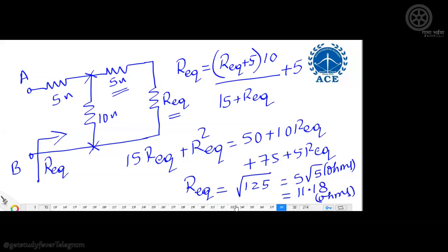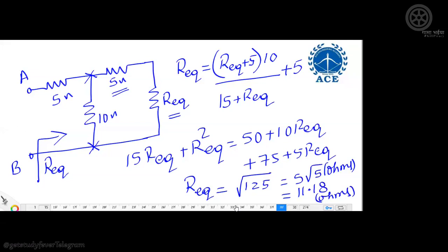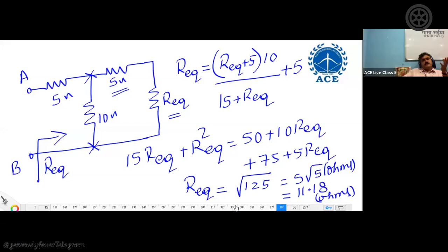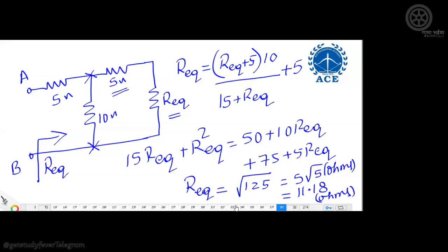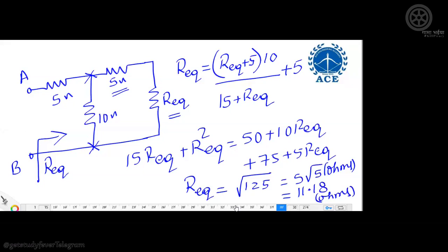But after, in the transient state, you took t equals 0 plus and t equals 0 minus for current. Yes, that will be there, because that will happen only on inductors and capacitors, not on resistors. Why will it happen, sir? Because they don't allow sudden changes. That is what I have proved with that integral part. Now, that second part of the integral is 0, because they don't allow sudden changes in current or voltages.